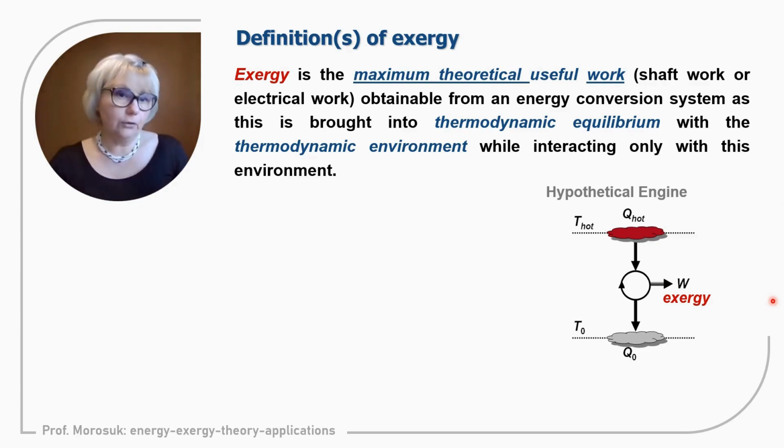I know publications where people say that the concept of exergy cannot be applied, for example, to refrigeration applications, because in refrigeration machines we are not producing exergy. This is not true, because the definition of exergy has an alternative definition related to processes below the environment. So the exergy concept can perfectly be applied to refrigeration and cryogenics.